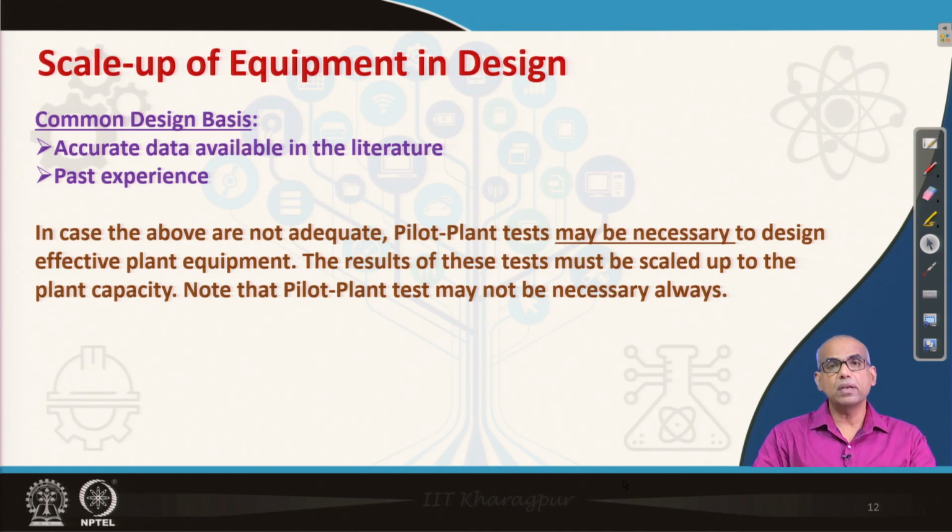So, pilot plant tests may be necessary to design effective plant equipment when you do not have adequate past experience or you do not have accurate data available in literature. The results of the pilot plant test must be scaled up to the plant capacity. But remember, the pilot plant test will not be necessary for design of every piece of equipment. We will shortly see the cases where pilot plant testing is always necessary and the cases where it is not always necessary.